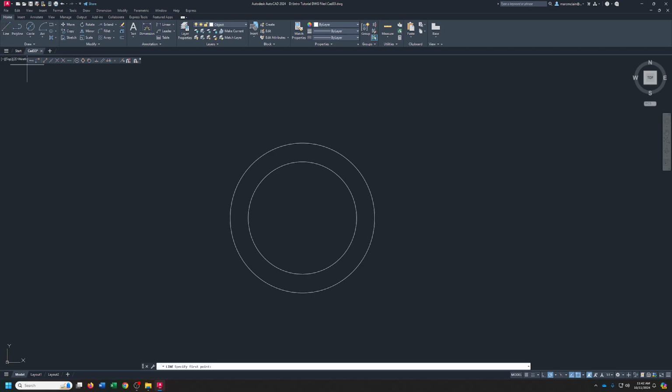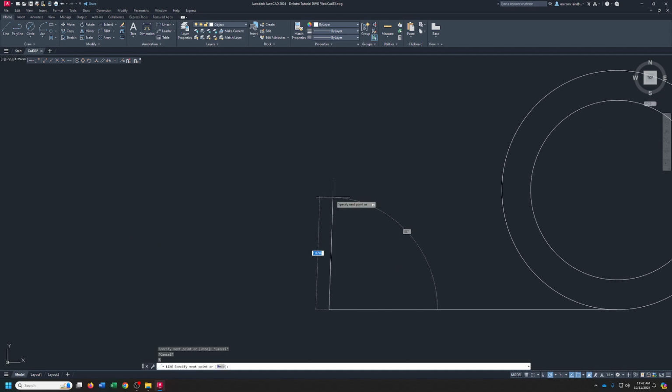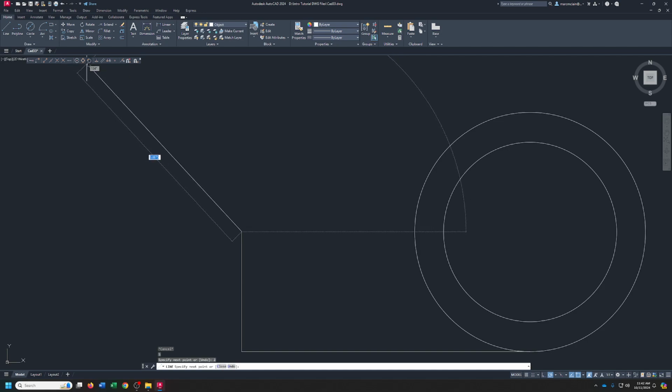All right, now we're going to start at the bottom of this thing, so quadrant bottom, and we're going to come out 5 inches to get to the front. Get it straight, 5 inches. And then we're going to come up 2 inches. We get the 2 inches because it's got a radius of 1, right? A radius of 1 would mean the diameter 2, so we're going to come up 2 inches. And then from there, we're going to go to the tangent of the 4-inch circle. There we go. Now I'll come back, and this comes back 1 inch, and then goes down.